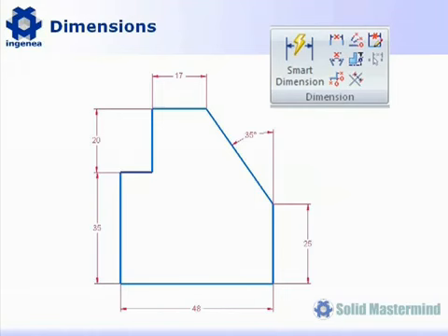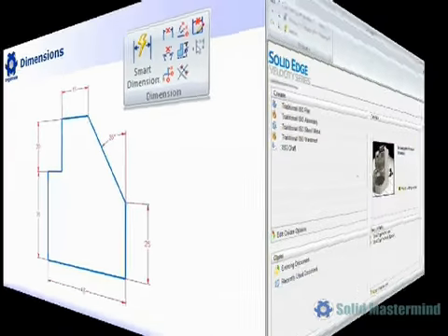In this second fundamental sketching session, we will be learning about how to control a sketch or profile using dimensions and parametric constraints. First, we'll take a look at the dimension tools available within the profile and sketch environment. Dimensions are very important as they are used to both label and control the size, location and orientation of the 2D geometry we draw in our sketches. Dimensions also provide parametric control over the geometry, meaning their values can be changed at any time. They work hand in hand with the geometric constraints that we'll be learning about in a few minutes.